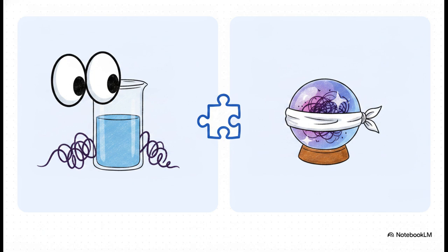Because feed-forward doesn't look at the final output, it relies heavily on having a really accurate process model. In industrial reality, because it's completely uneconomical to measure every single little disturbance, engineers usually combine both. They use feed-forward to catch the big measured disturbances and feedback to clean up the unmeasured ones. Best of both worlds, right?